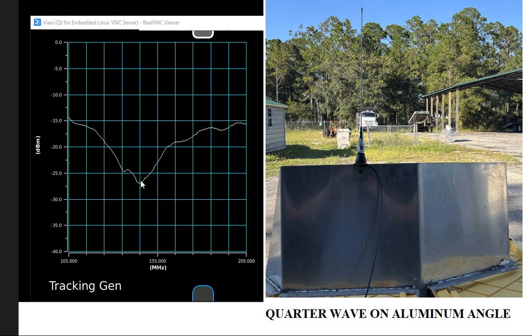In order to pull this back over, you would need to shorten the antenna. You'd have to cut it some to get it back over here, like a half inch, an inch. So this is an example of how anytime you put one of these antennas in a weird spot, it could change not only the return loss, but also the resonant frequency.